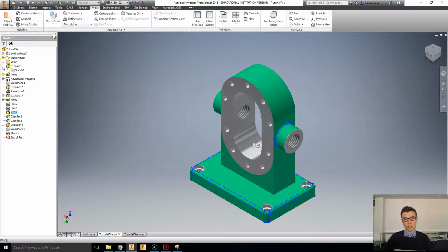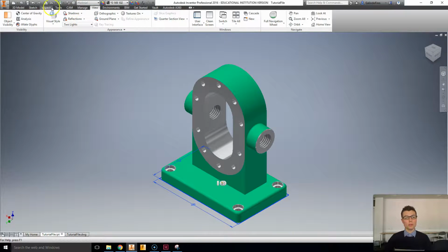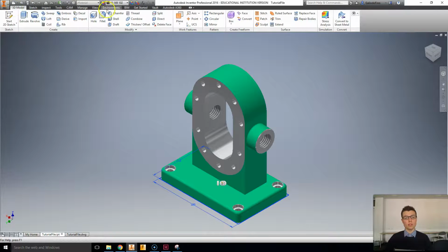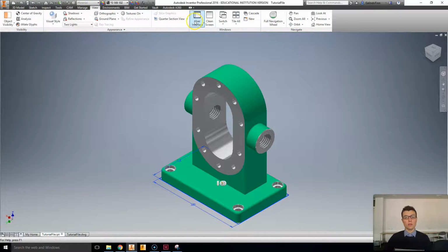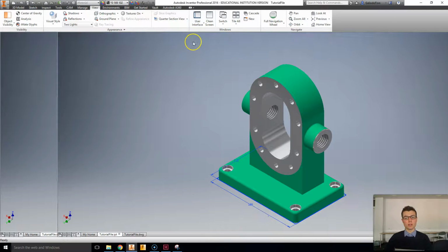Commonly, a feature, if it's 3D, will have utilized a 2D sketch, and you can see this is viewable under the expansion button of the 3D feature here as the sketch in 2D, and that visualizes it there again in the 3D workspace. If you should ever lose your browser on the left here of the screen, all you need to do is go to the View option of the ribbon. So say you're on 3D model, you'd select View. Now we're interacting with the user interface, so we're going to select this button and reselect browser so it's seen.